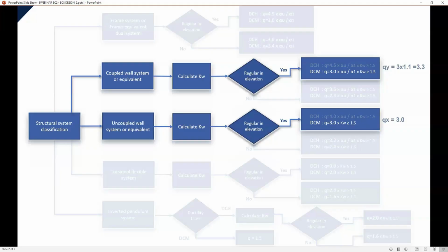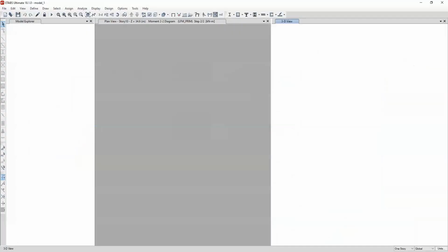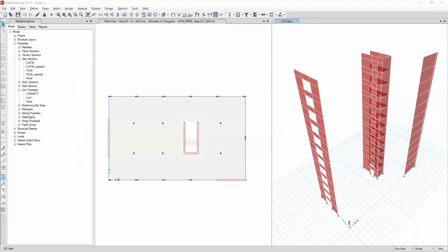An important aspect is that the checks we perform are independent by story. It is natural that if we based our checks on shears or story drifts, we would get different results per floor. If the 15% limit is met on some floors but not on others, it is an engineering decision for the designer to justify why they considered the distinction between primary and secondary structures appropriate. We will keep this philosophy regarding drifts and story displacements in mind and see how to proceed. Let's look at how to calculate the influence of secondary elements on the structure's resistance in our model.